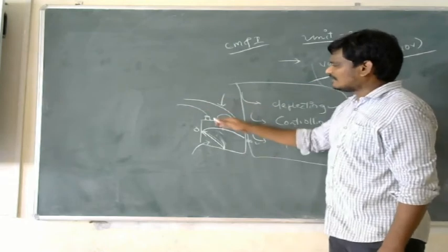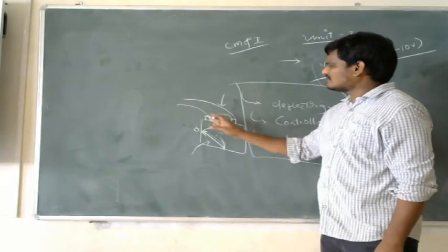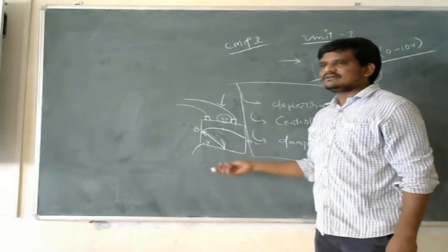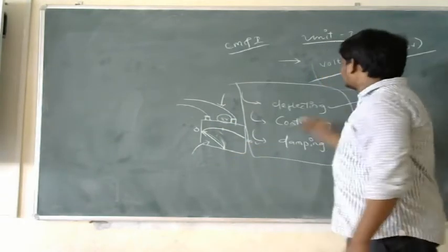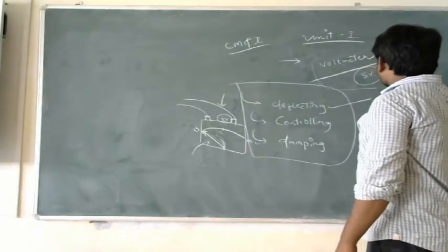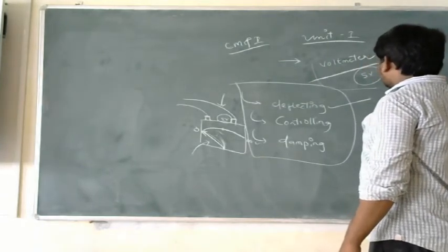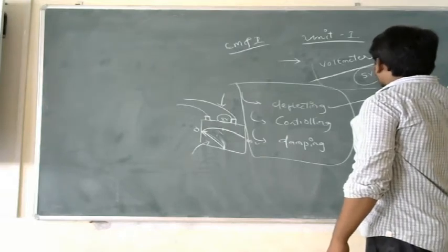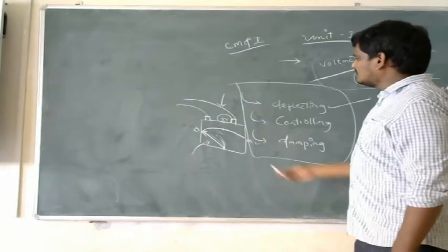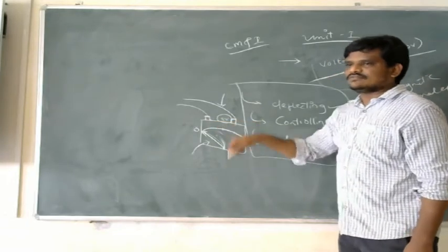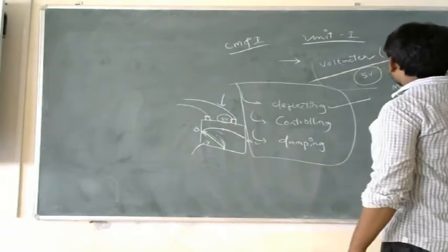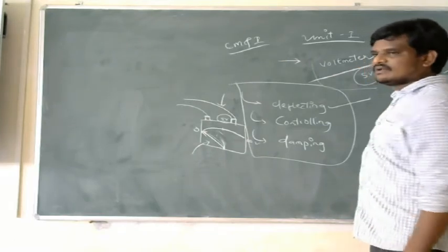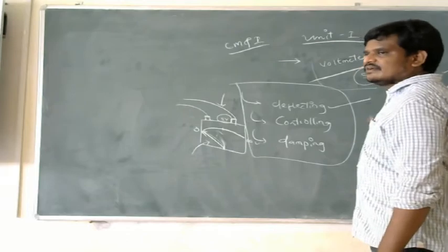The first thing is how the force has been applied in this particular voltmeter here. I am giving the input parameter as voltage, or else I am applying some amount of voltage or current to this particular meter. How has this current been converted into force here? By using the magnetic effect, or by using the thermal effect, or by using any other effects. You can convert the input parameter current into force by using any one of the effects we are going to discuss here, either a magnetic effect, a thermal effect, an inductance effect or mutual conductance.